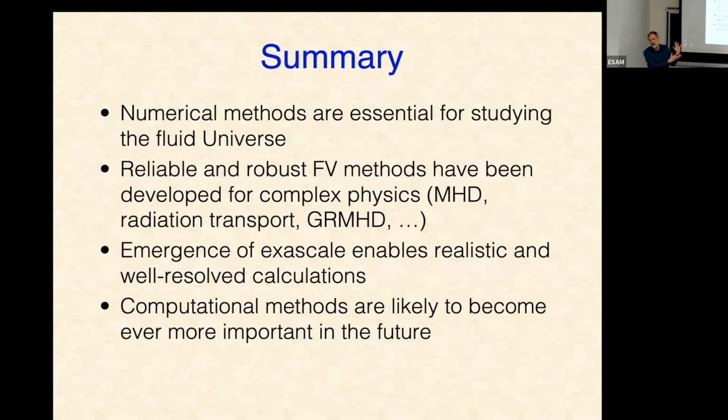And then the resulting hierarchy of meshes is whatever it is that you lay down. Any block in the mesh can always be refined again into 4 more blocks, or 8 in 3D, depending on whatever criteria you choose. Okay, so the philosophy here is to choose the right refinement criteria based on the problem. Well, that gets back to this art of AMR, namely, you will get a different hierarchy depending on which criteria you choose. You can run exactly the same problem, choose 2 different mesh refinement strategies, and get 2 different meshes and 2 different solutions. And if that affects the outcome of the things you're trying to measure, that's very bad. You have to then figure out what is the generic refinement criterion you need. This is not discussed very much, and most people don't pay much attention to it, but it's a fact of life that you have to be very careful about what the refinement criteria are and make sure you understand exactly how that affects the solution you get.